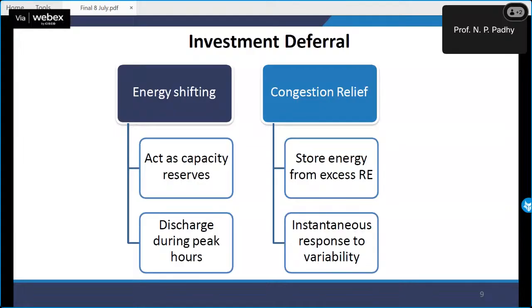If you procure the power for 100 megawatt, then you have to pay for 100 megawatt throughout the day. So what the distribution companies normally do is buy energy for 50, and in the peak hours they meet the demand with some external sources, and probably the battery can be used to charge and discharge during peak hours. That is the strategy most of the distribution companies adopt today.